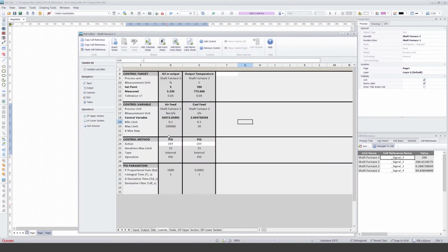Then next we can try to adjust the controls. So we have 2 PID controls here. And now we set up the P parameter for the 1 second time step. We have changed it to 1 minute afterwards. So I will decrease the proportional gain a little bit and then see how it goes. So if we run the model, okay, seems to be behaving maybe okay.